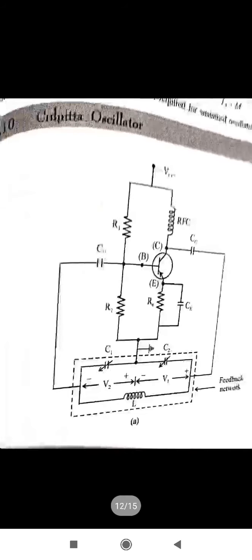Next, for the minimum condition of sustained oscillations, when the real part of the determinant matrix is equal to 0, we get the condition in terms of del, L2 plus M upon L1 plus M, as denoted by this matrix. For the Colpitts oscillator the diagram and conditions are the same, but the change is that we have used two capacitors in parallel with the L equivalent circuit.